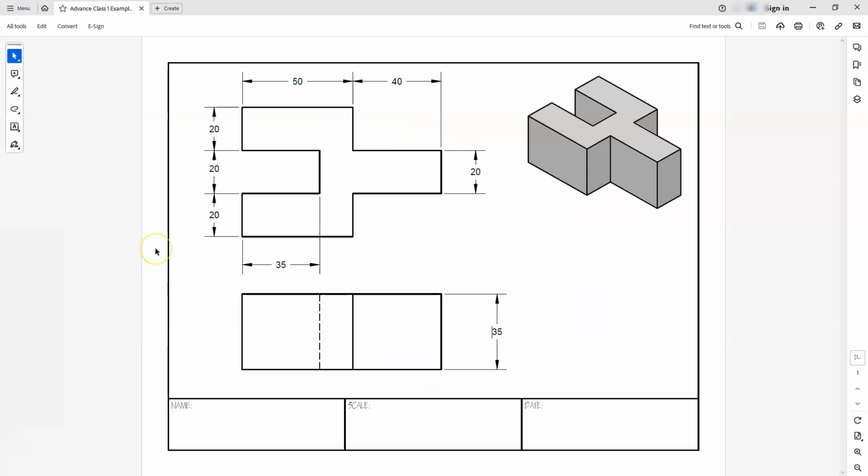Okay, so here on the drawing, you can see that the one view that I can create this in happens to be the top view. So that's why I'm going to select the top view. When I come back into Inventor, I'll select the one that's showing me the top view. I'll try to orient this to the right view, but I'm not really concerned with that. I'm more concerned with at least getting it in the right orientation.